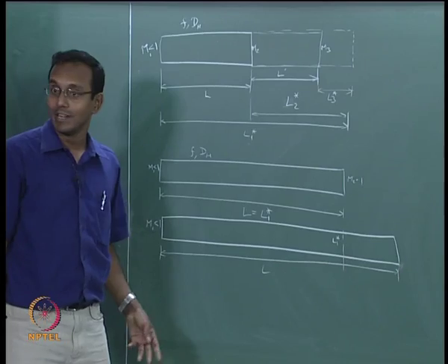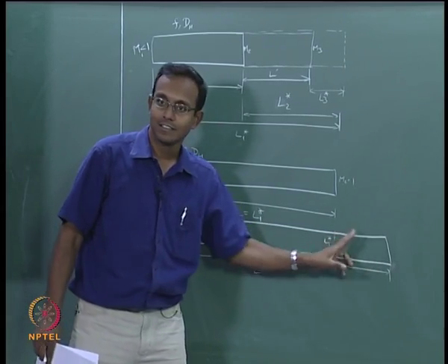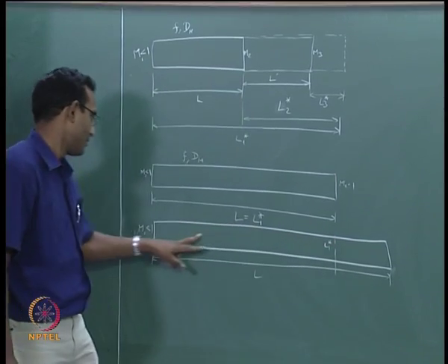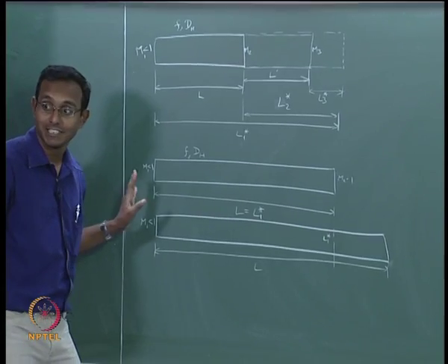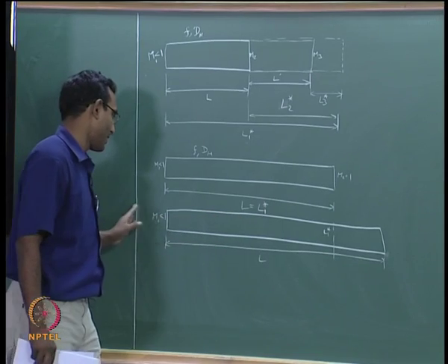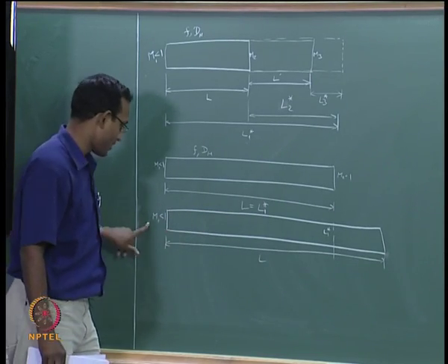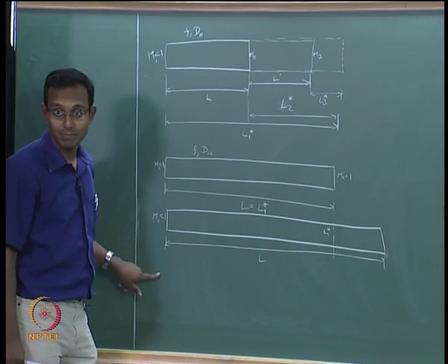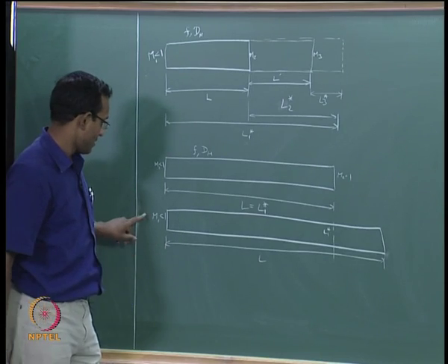What will the flow do? It will decrease, it will send out extra compression waves from this excess length, such that those compression waves go, and it is subsonic, so it will go faster, it will reach this point. We are thinking only steady state as of now. So, all those compression waves will make this flow come in slower. So, M1 will now change to M1 prime, which will be less than M1 value, okay, such that it is